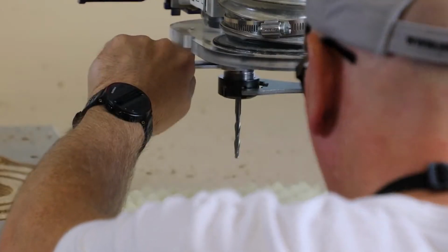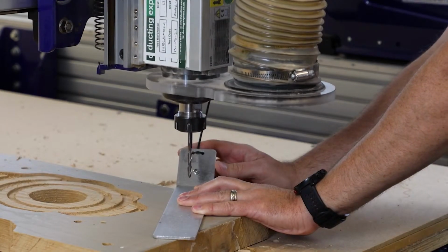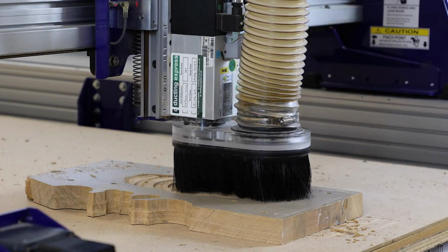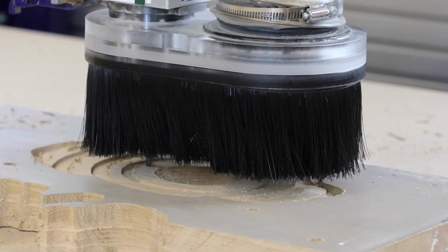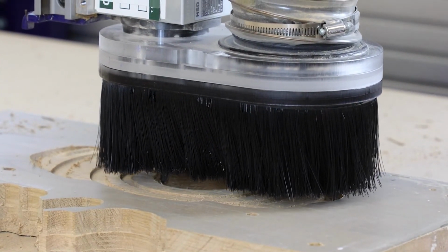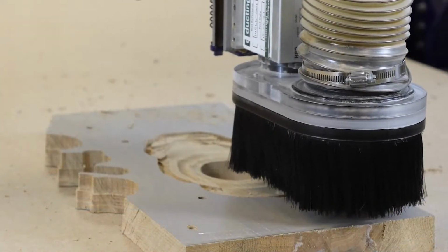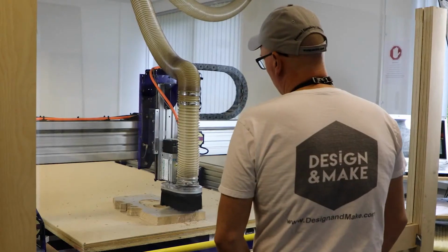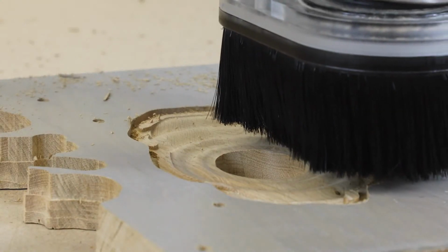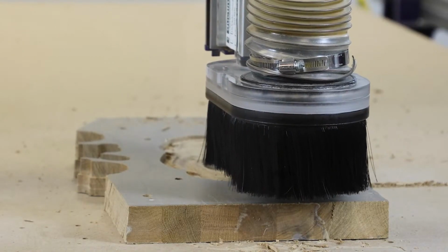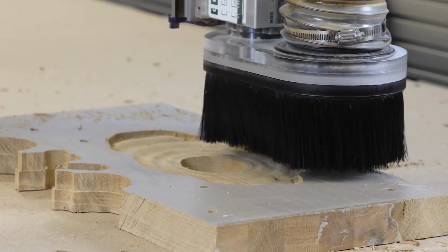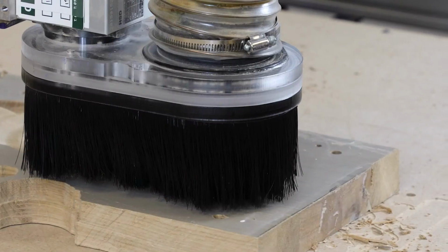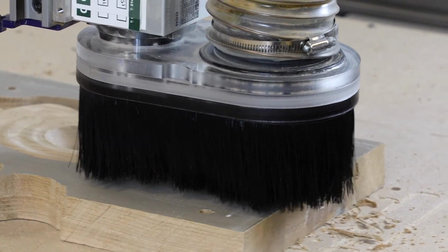And the center looks great with all those nice steps in there. And we put back in that ball nose again, and we're going to go in and do our finishing pass. Now this finishing pass did make me a bit nervous because of that tall straight wall in the middle of that hole, but it didn't seem to have any effect on it at all. It's an offset toolpath, so it worked its way from the inside out, which gave me some kind of nice machine lines to deal with. I didn't quite get them sanded out, they'd still look pretty nice.